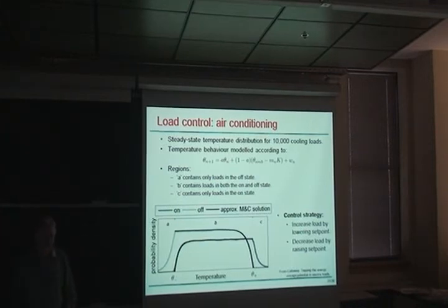There's an enormous amount of capability for controlling load that's air conditioning type load or energy storage type load. With an air conditioner, you set the set point to a certain temperature, but it operates on a hysteresis band. So you might set the temperature to 68 degrees. It will actually vary between 67 and 69. You're kind of oblivious to that, but it's doing that kind of tracking all the time.